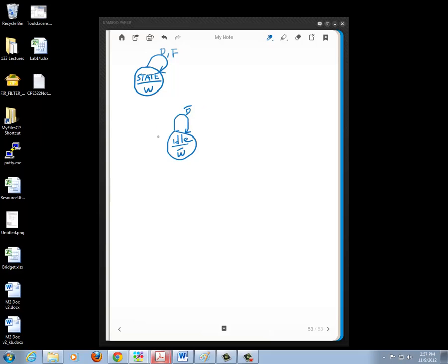Now, what if I get the dry input? Dry means I better start watering, right? So I'm going to move to the next state. I'm going to call this state the water state. And in my water state, that means I want to actually give this thing water. So in my water state, that's because I got the dry signal, so D caused me to move to the water state, which will turn on the water, and I want to have the water on so long as I'm not flooded. So I'm going to say, so long as I have a no flood input, I'm going to keep watering. Once I get the flood signal, then I want to stop watering, so I want to go back to the idle state.